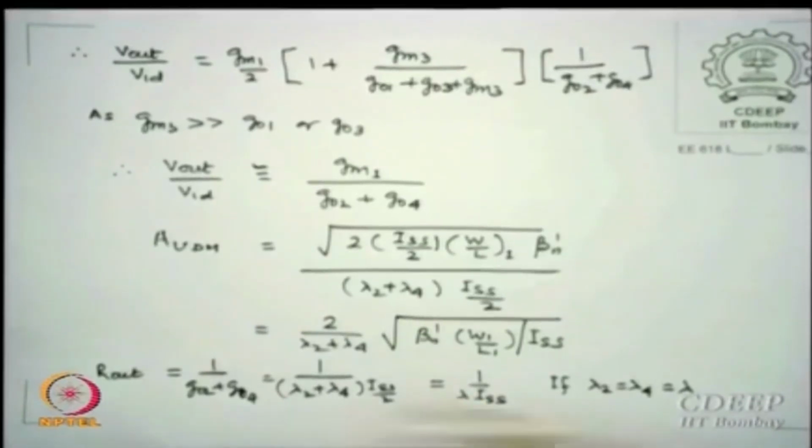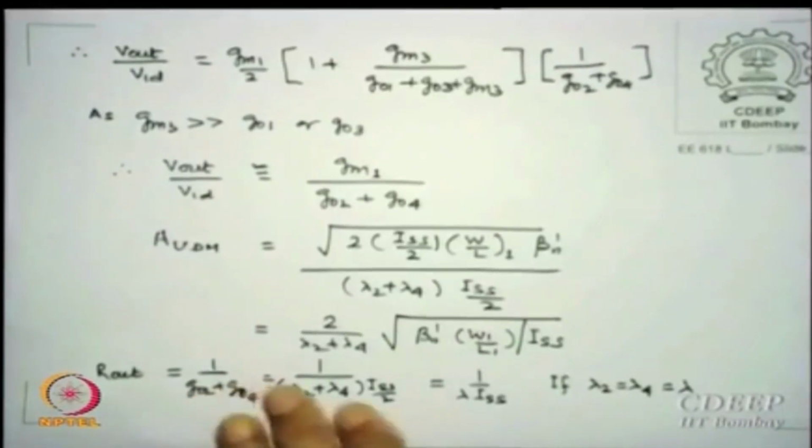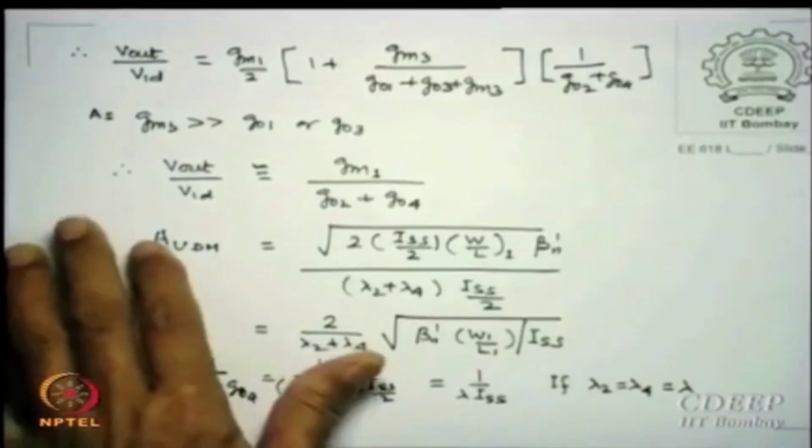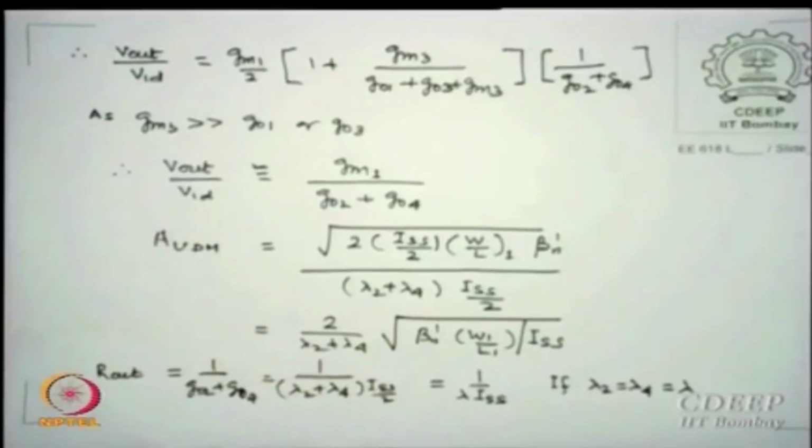Either by the transistor which I will put for the source ISS, either the size of that transistor or the bias of that transistor, or I mirror it from some other source which will force exactly the current which I wish. Okay, I will show you mirrored ones later when I calculate. So essentially I am trying to tell you that the designer can relate, if you want so much gain, 10 to the power 4, 10 to the power whatever number you say.